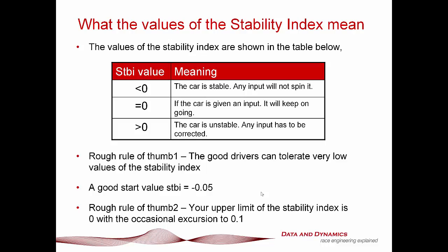Back in the late 60s and 1970s, aircraft designers cottoned on to the fact that if they wanted to make their fighter aircraft as maneuverable as possible, bleeding the least amount of energy possible, they were going to have to go unstable. That trend was started off with aircraft such as the F-16 and the F-18, because, bottom line, that's where the grip was, and it's why with those aircraft you started to see pitch stability augmentation systems emerge.